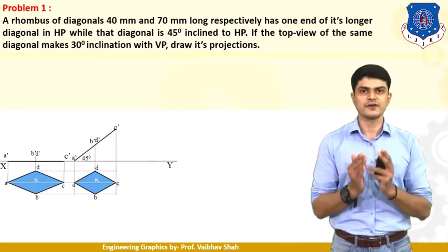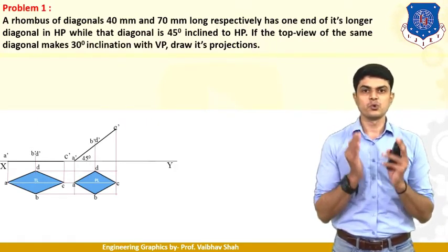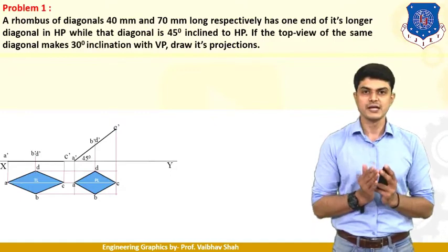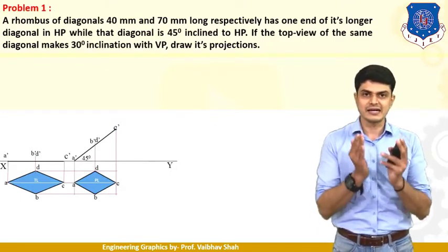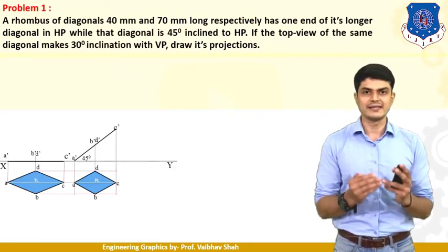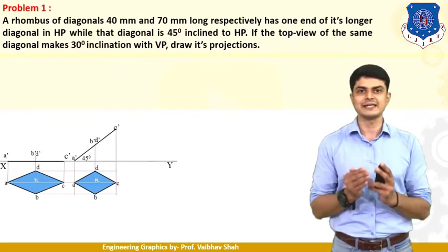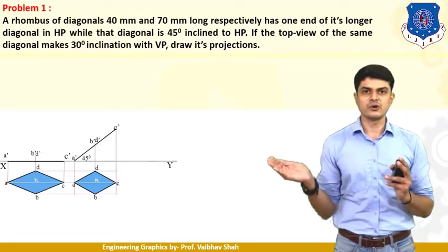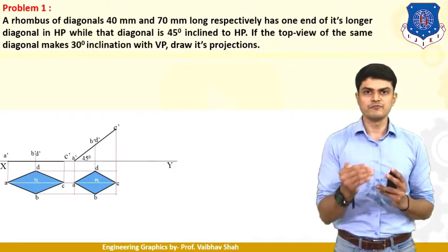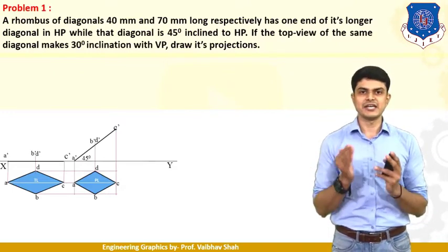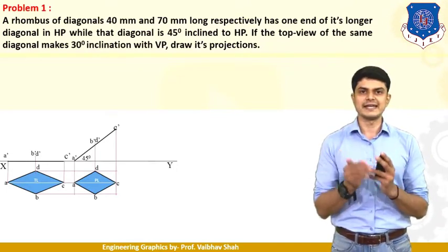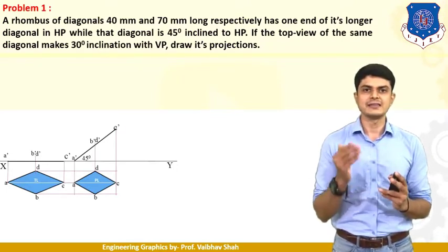So it is known as a true length of an object because we have used the true length whichever is given in our example, which is 70 mm. So which is what? True length of an object. But in second stage, when your line gets inclined, you are having the second view as your top view, which is not of a true length and which we can define as our plan length, or you can say top view. So here the horizontal line is described by a plan length, or you can say a top view. So the diagonal is changing in the length in the second view.